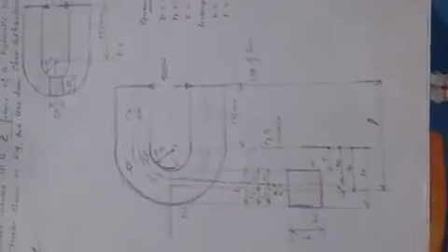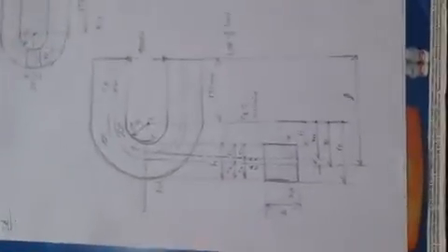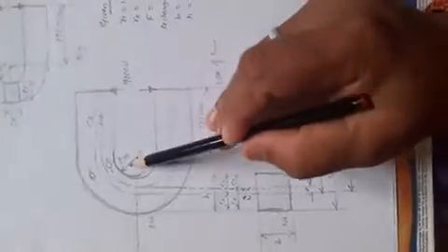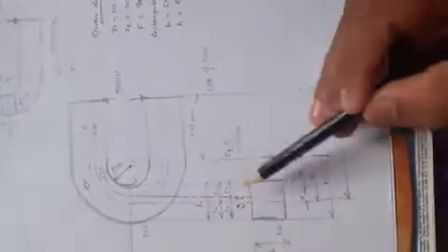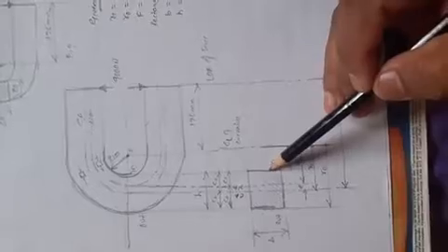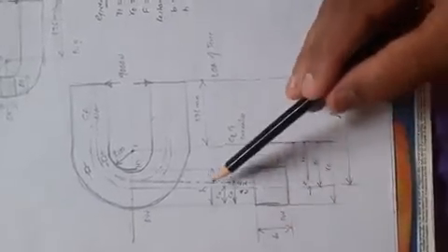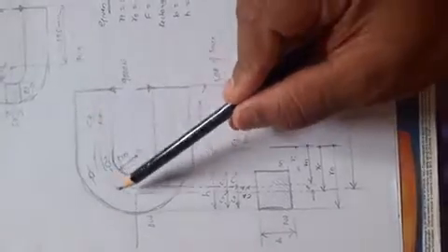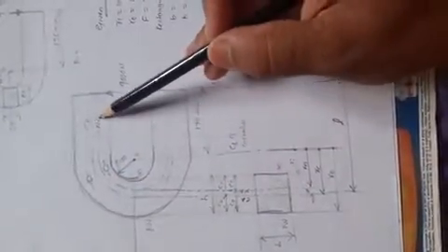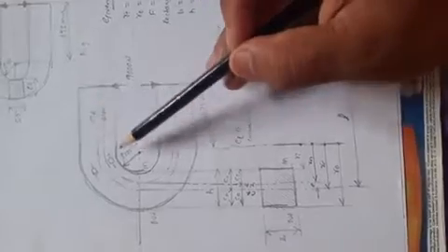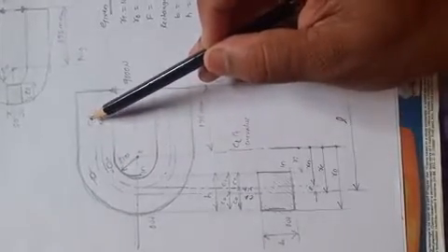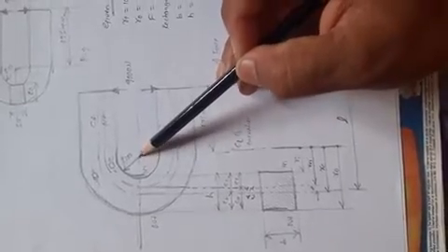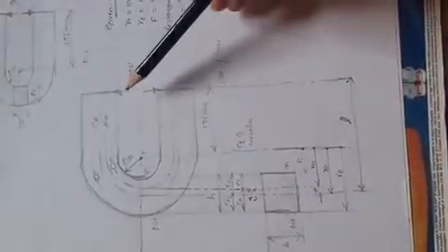After that, redraw the sketch. How to solve this problem? Redraw the sketch like this, the C frame, and also draw the cross section below it. What type of cross section? Rectangular cross section, with breadth and height. The centroidal axis is the center of the geometry, and the neutral axis always lies towards the center of curvature, between the centroidal axis and the center of curvature, right?